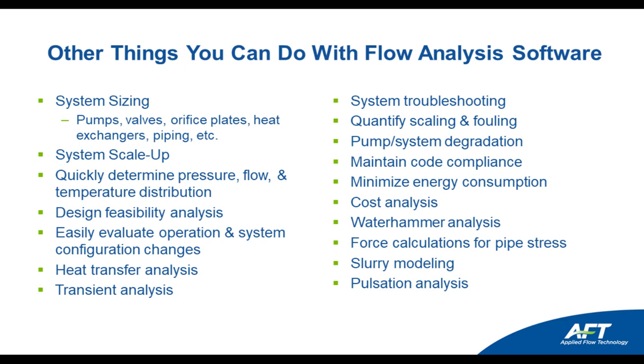Well, what happened? Sure enough, when they turned on the flows, the new heat exchangers didn't get any of the flow because the pumps were already maxed out, serving all of the rest of the flow demands. So the moral of the story is get it right the first time and take the time to do your flow analysis to prevent future problems and ensure that your expansions and your designs are actually going to work.